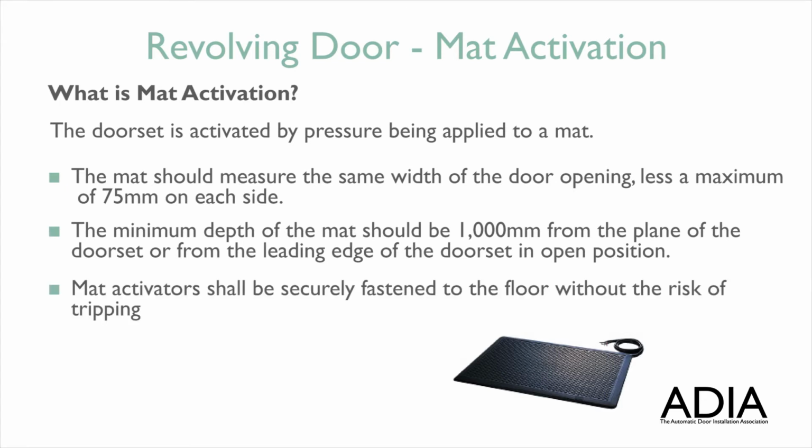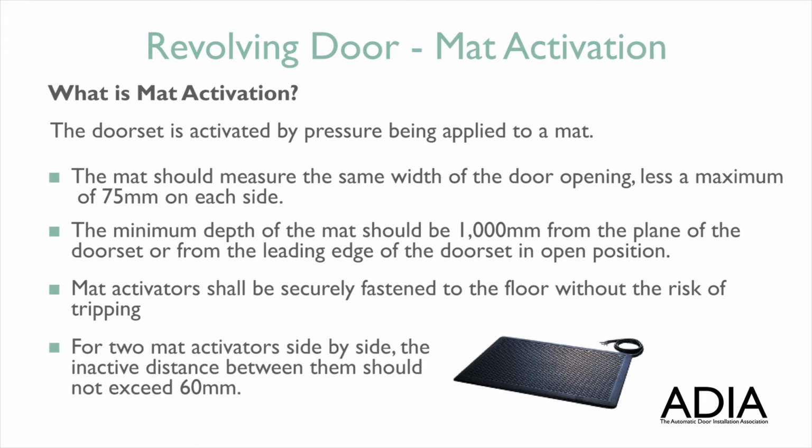Mat activators shall be securely fastened to the floor without the risk of tripping. For two mat activators side by side, the inactive distance between them should not exceed 60 mm.